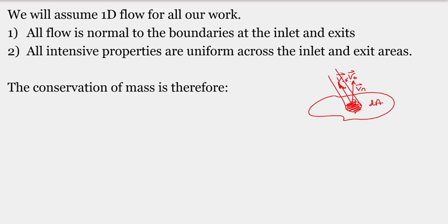So again, this is the velocity associated with the mass that's crossing the system boundary. So we know that for mass crossing that little differential control volume for some time period, delta t, and we're going to take the limit, you can see, I hope, where this is headed, where delta t is very, very small, that amount of mass crossing the system boundary is simply given by the volume of that slant cylinder. So if we project this area here, let me be a little bit more clear here and do this. We're going to take these off, and I'm going to simplify this sketch so we can see it perhaps a little better.